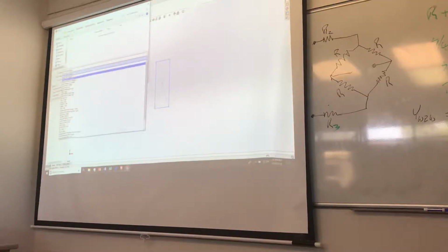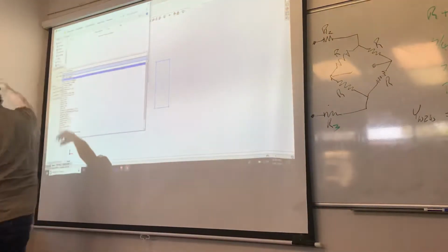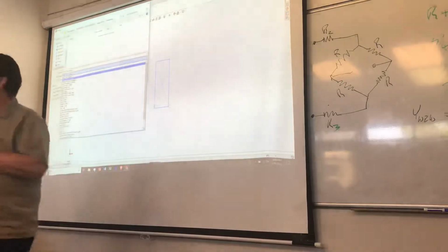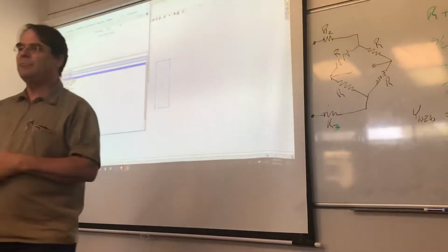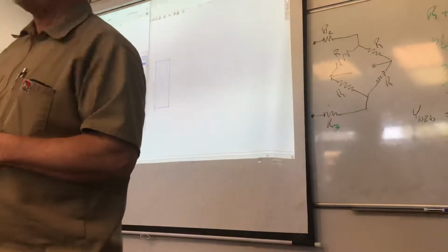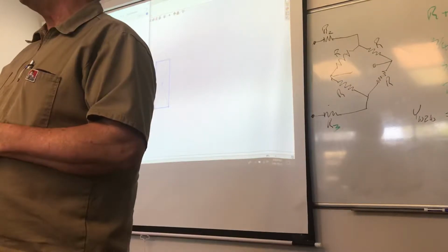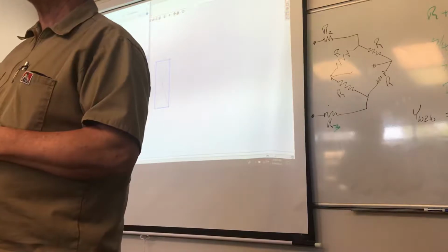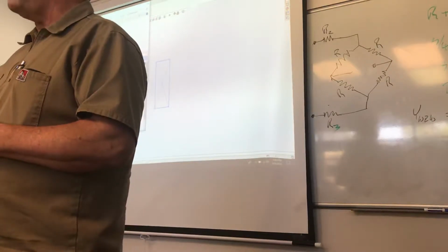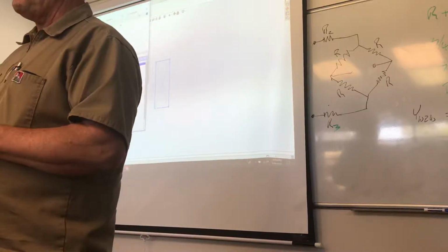Okay. Now, questions are asked. Do I want to save to this long path? Program data, which it doesn't actually show, but it's SolidWorks. I think it's program data, SolidWorks 18, design library, Weldments. It's as good a place as any. You're going to have to go move it anyway. I don't really care where it saves at this point, as long as it saves somewhere.